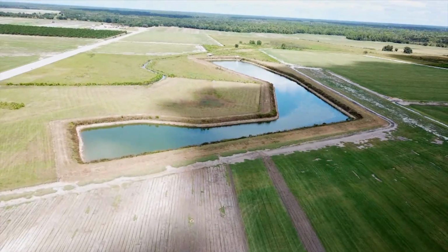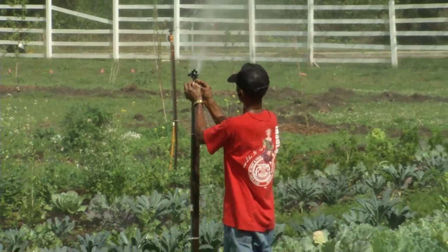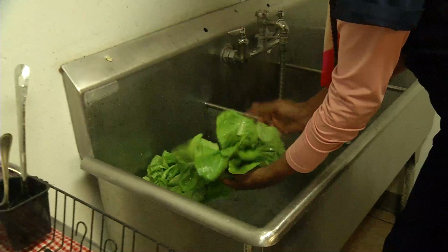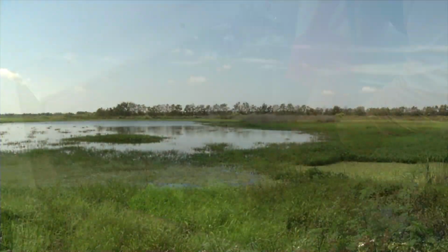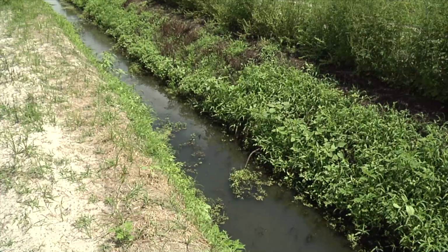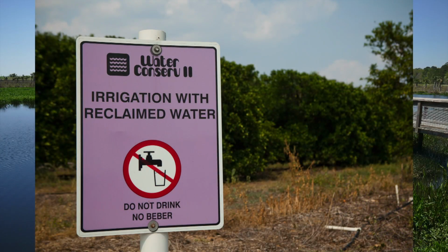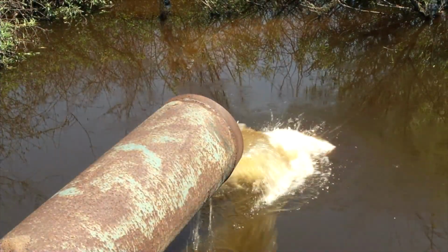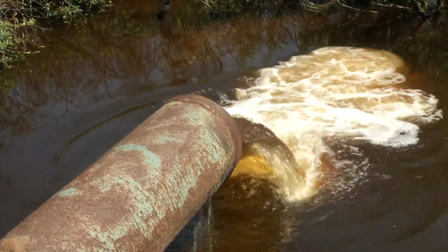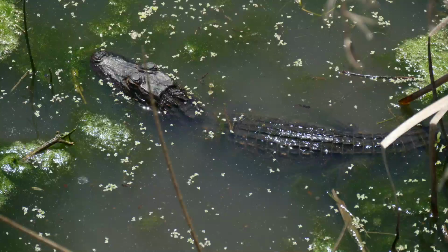Surface water is considered the highest risk of the water sources, but can still be used during growing and, if treated, during post-harvest activities. Surface water includes water that is from open bodies of water like streams, rivers, canals, lakes, and ponds, and water that has been reclaimed. It also includes water from other sources that is recirculated, stored, or distributed in open systems, even collected rainwater. It's considered the most risky because it is exposed to the environment and can be easily contaminated.